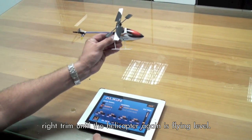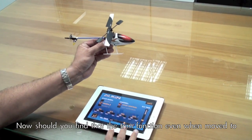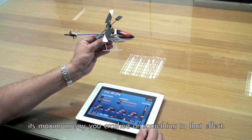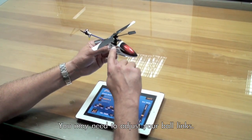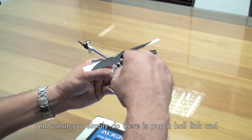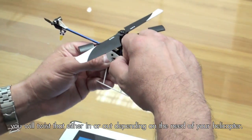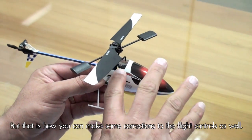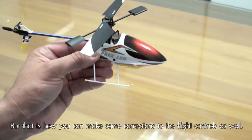Now, should you find that the trim function, even when moved to its maximum, say you crash or something to that effect, you may need to adjust your ball links. And what you simply do there is pop a ball link, and then you'll twist that either in or out depending on the need of your helicopter. But that's how you make some corrections to the flight control as well.